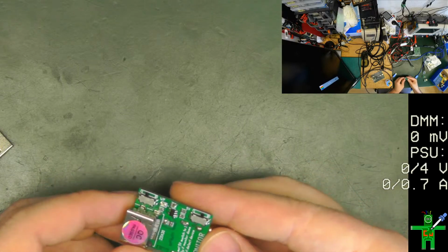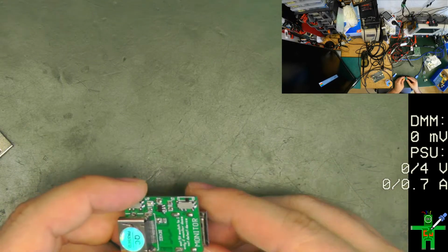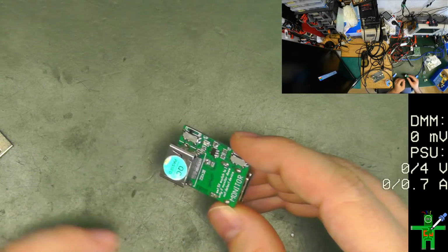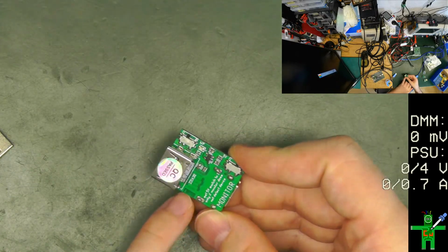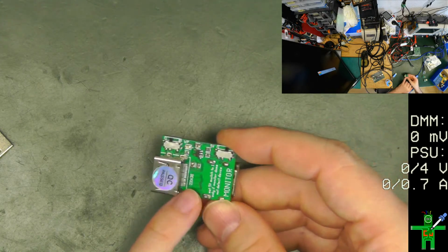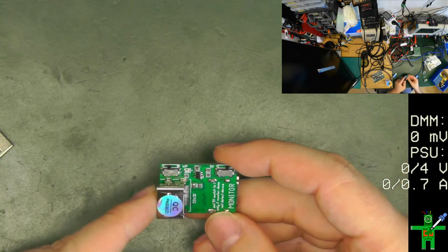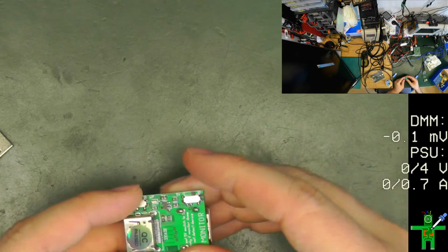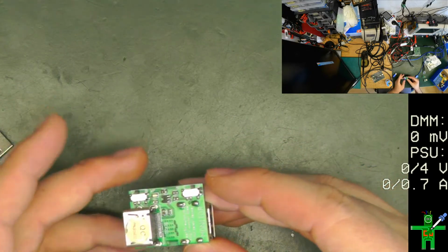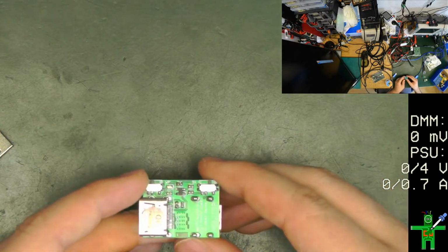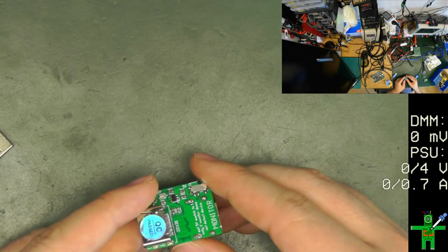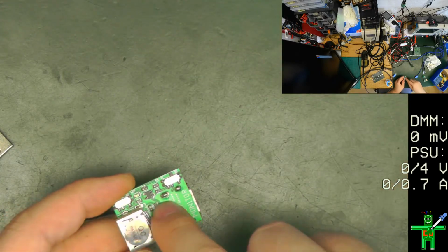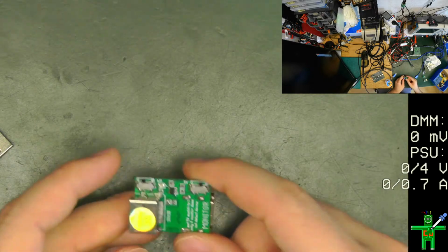USB 2 is very reliable. It's not really a high-speed data signal. HDMI is 300 megahertz. This is a completely different ballpark with the clock. And this was my first opportunity to route high-speed signals, and it wasn't perfect. It was radiating, so I had to change. But the device works. It's just radiating a bit, so you can listen to it, where you can just place an antenna next to it, and then you can grab the video signal.